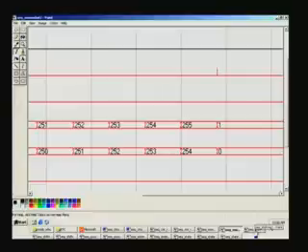Yes. But still that glitch is likely to be there, isn't it? Which one? No, that won't be there, because that signal itself will be removed. This signal is the result of ORing two things, right? Reset counter, reset being active and counter being 255. We have clubbed, that is why this, it is not a glitch as I mentioned, right. In the RTL coding guidelines, I think we saw how glitches are formed. It is because of difference in path delays. So now we will move on to the shift register.